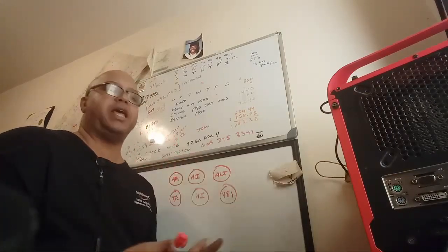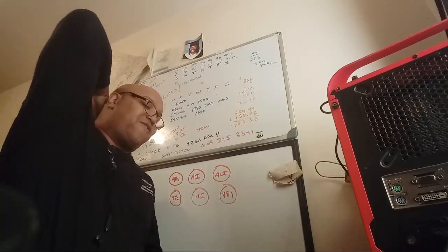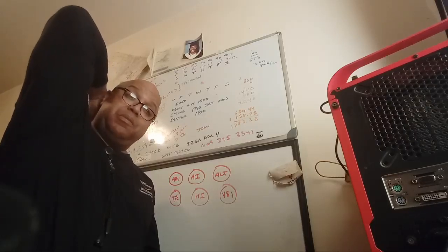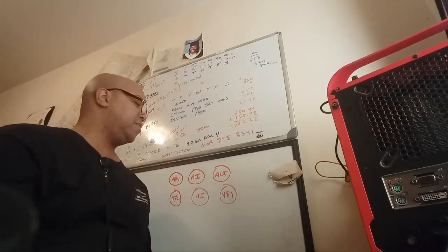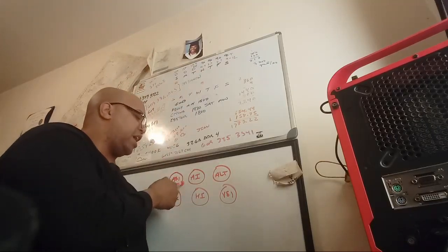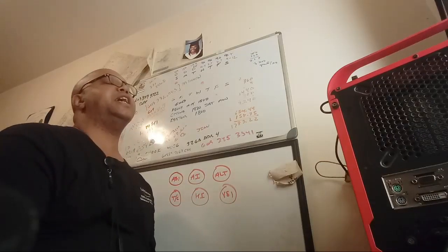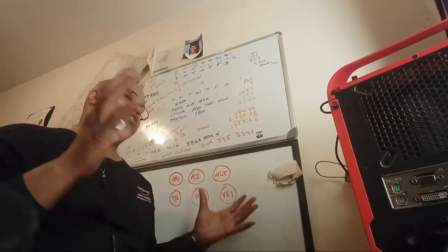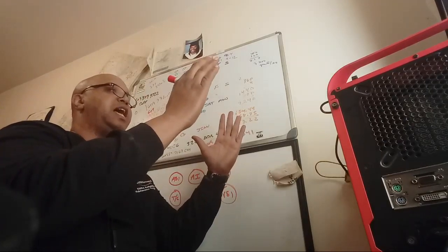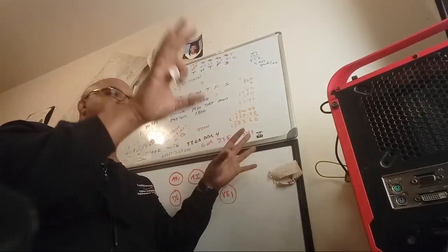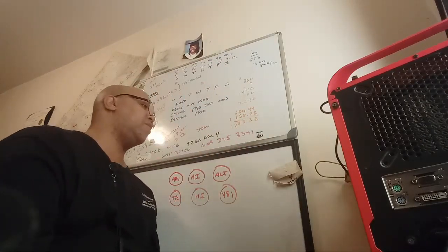Now, in some more advanced aircraft, you will not have these dials here. You might have a head-up display. You may have an EFIS, which is an electronic flight instrument information system. I think I've showed you on the simulator a couple of ways that they could be displayed. But you will get a lot of the same information like airspeed, attitude, altitude, heading, and possibly vertical speed indications. So what they've done is they've just consolidated it and put it on a heads-up display glass, so you can keep your eyes outside of the aircraft and see what's going on instead of peering down into an instrument panel.